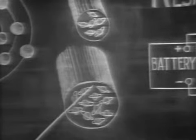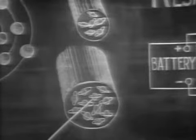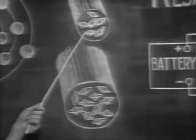This view of a large and small wire shows that the large wire contains more atoms. With more atoms, there are more electrons available. And with more electrons available, it will pass current easier than the small wire. Then as the diameter of the material increases, its resistance decreases.